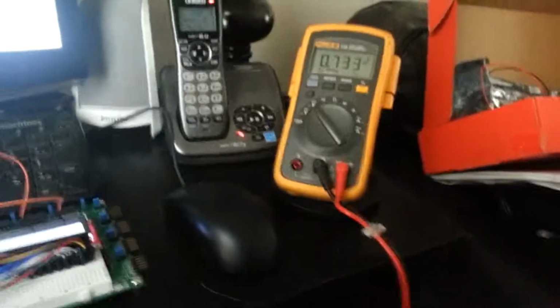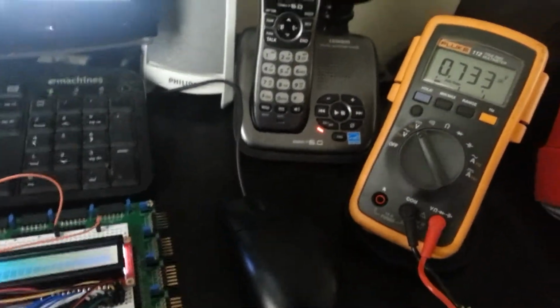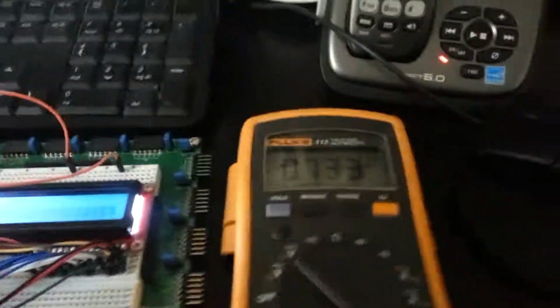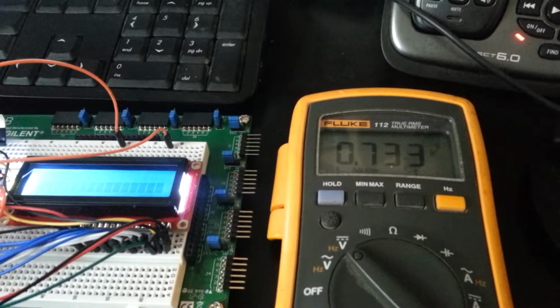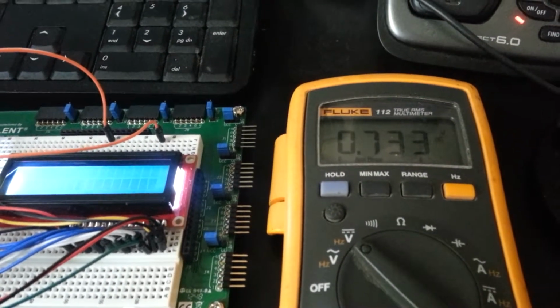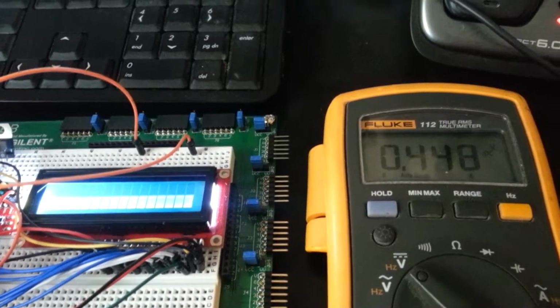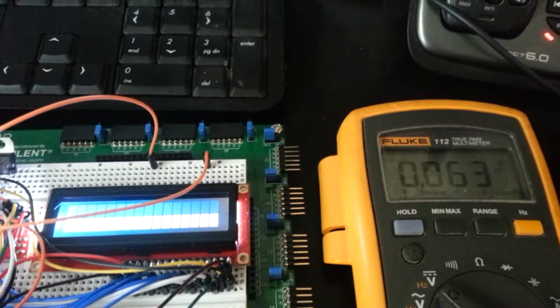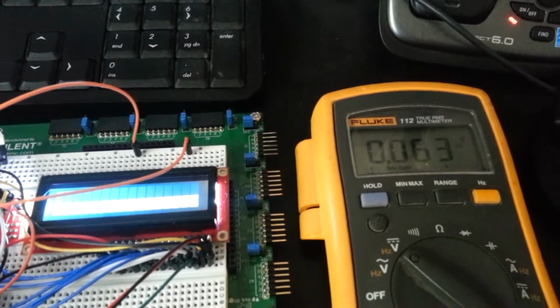So let's go ahead and make some changes, and you should be able to see here. I'll try to get them both put down so you can actually see the changes occurring. Alright, so there's the multimeter, there's the display. Let's start playing with some of these switches and see what happens. I just changed the switches and I'm about to hit begin. You can see that the actual contrast changed, and the voltage changed. Let's do it again. We went all the way down to 0, and you can see that we have full contrast on there. Let's bring it all the way up to 3.3 and see what it does.